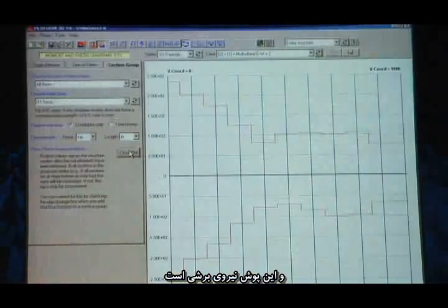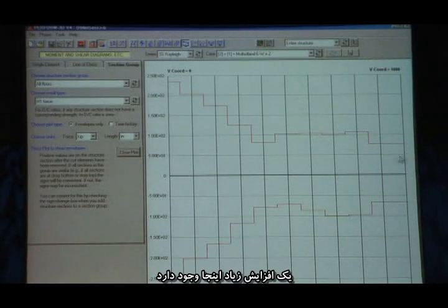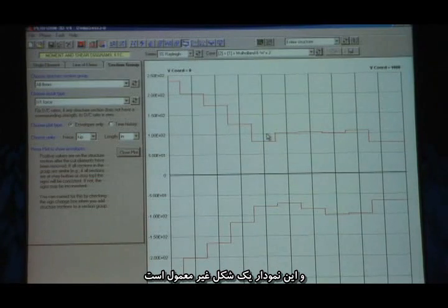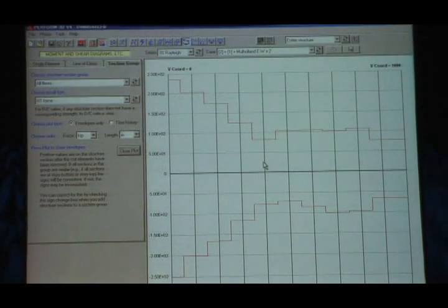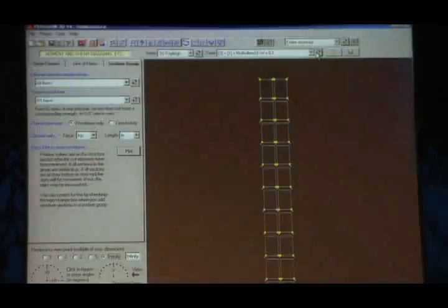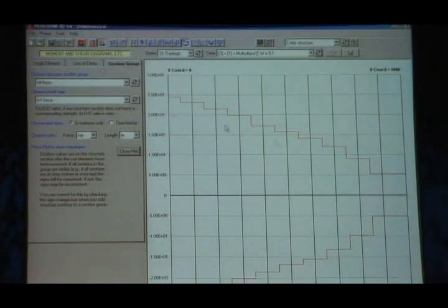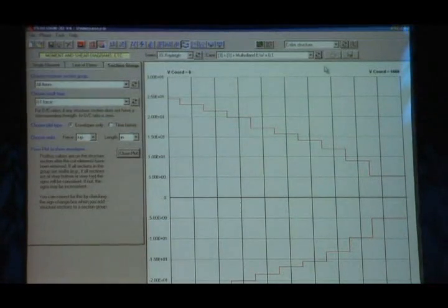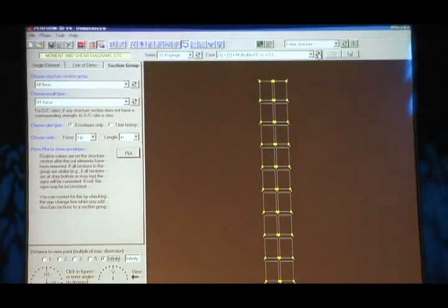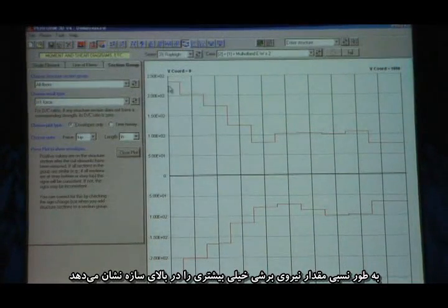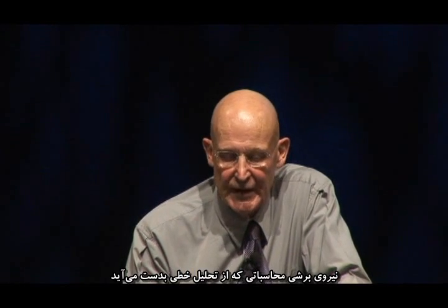Okay. Now this is the shear force envelope. It's a little bit big up in here, and it's a little unusual shape. And that is for the strong earthquake. Now, let me do it for the weak earthquake. Again, this is shear force. It's pretty much a straight line. The 2 shapes are quite different. Going back again to the nonlinear case, it's not a straight line. Relatively, it's showing much higher shear forces up here at the top of the building. So here's a case where the shear forces that you calculate from a linear analysis are quite different from the shear force distribution that you would get when you do a nonlinear analysis.